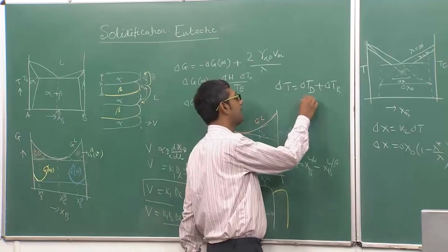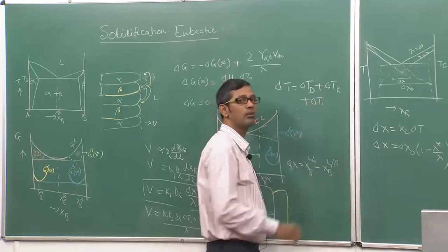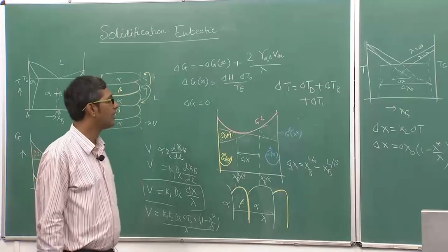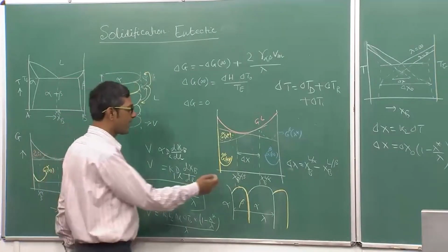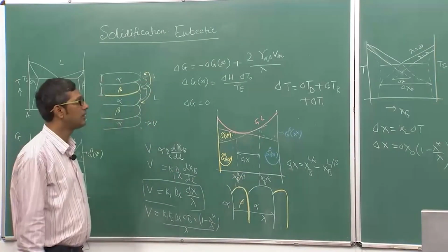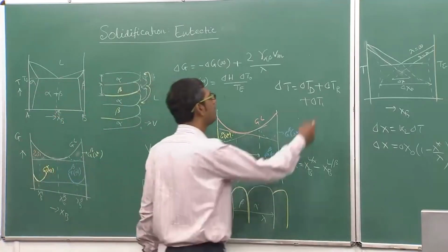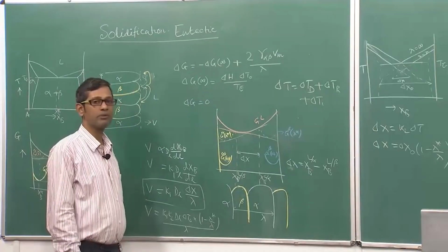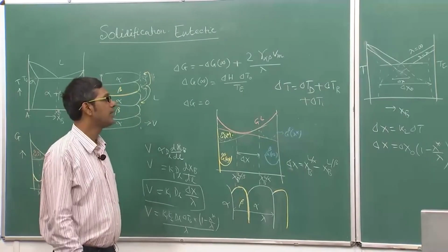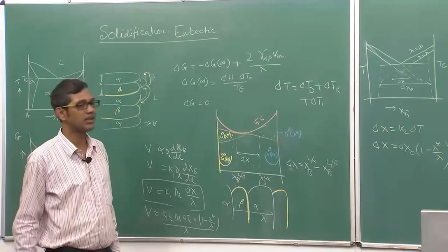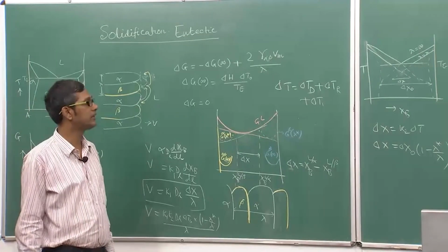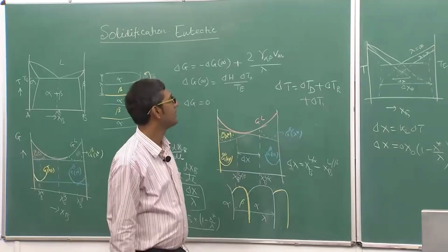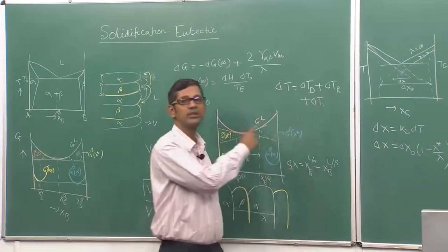Sometimes people also add another part, known as interfacial undercooling. This corresponds to the atomic jump from the liquid to the solid, and the undercooling required for it. Normally it is very low when the interface is rough, so the atoms can easily jump. But when the interface is faceted, like in aluminum-silicon type eutectics, this value is very high, and one must add this component to the total undercooling equation.